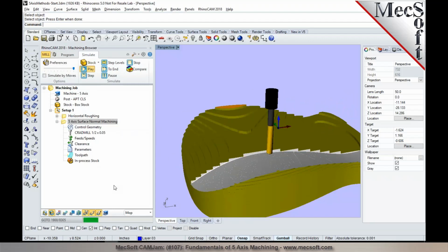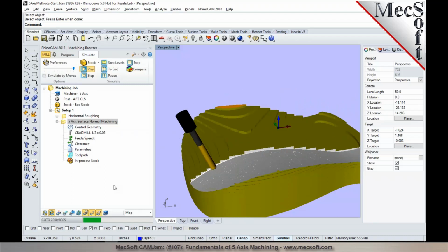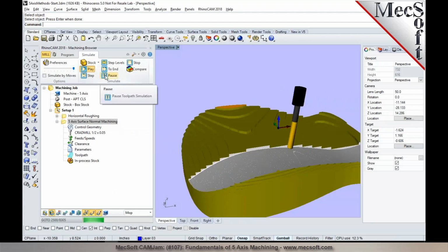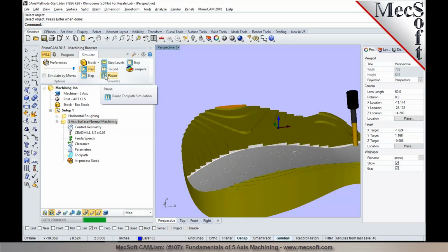Yeah, I think I also want to emphasize it really does affect your quality. I'm sorry, Uday, because if you increase the distance between two points, which is basically how far apart the toolpath points are spaced, you could conceivably make that quite large and actually gouge into your drive surfaces.